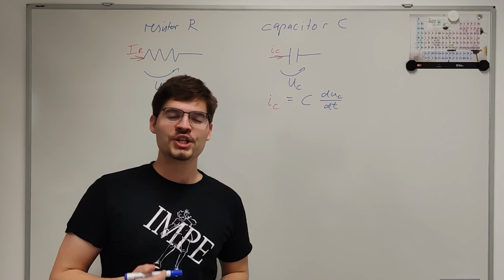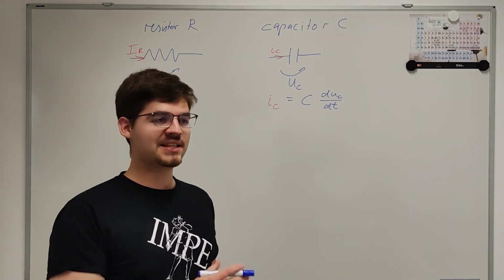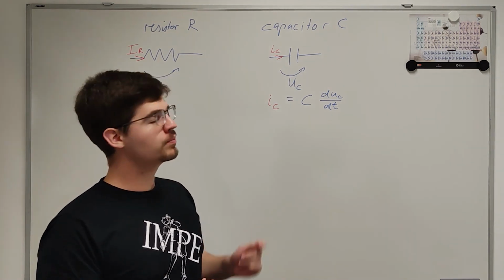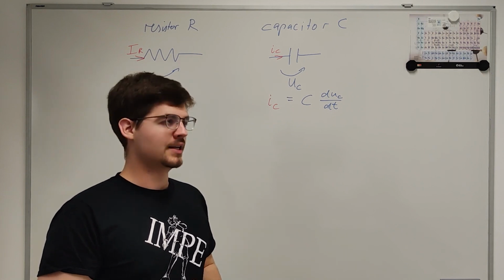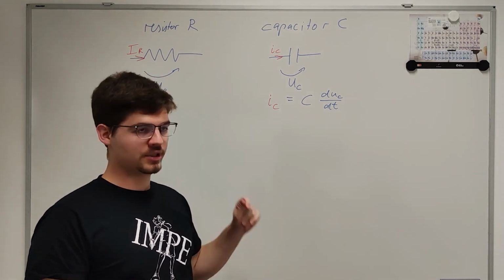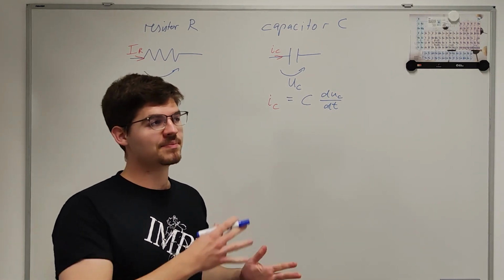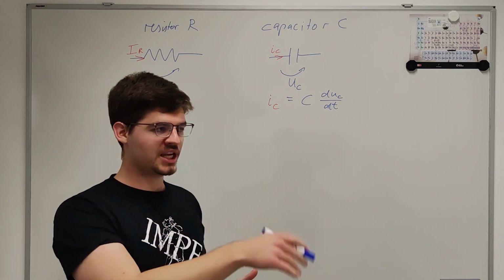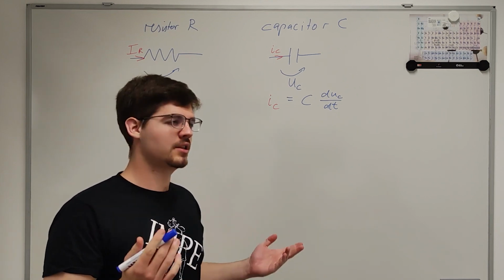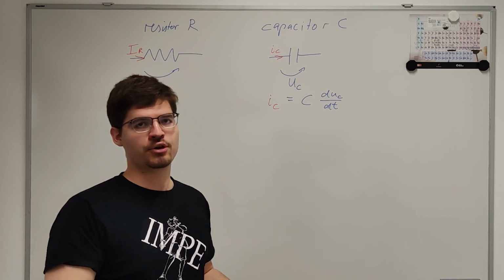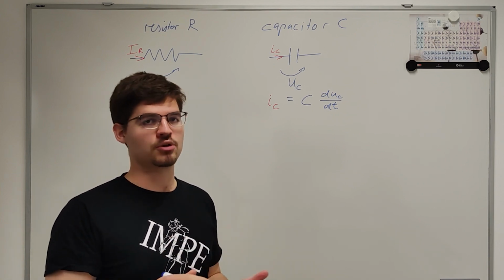Alright, we just considered the response of our basic circuit elements to a voltage step. Now, as we have seen, the current in the capacitor is transient. So we have a very large current spike, theoretically infinite, but the stationary current response to such a voltage step is zero.